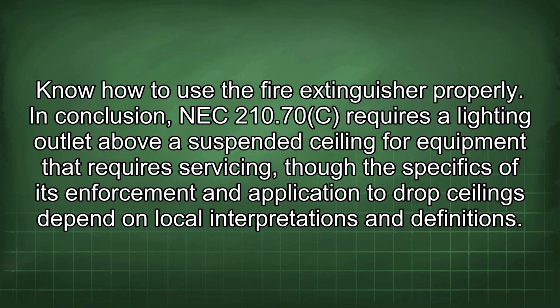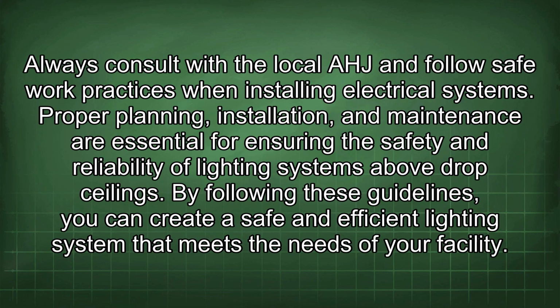In conclusion, NEC 210.70 requires a lighting outlet above a suspended ceiling for equipment that requires servicing, but the specifics of its enforcement and application to drop ceilings depend on local interpretations and definitions. Always consult with the local AHJ and follow safe work practices when installing electrical systems.